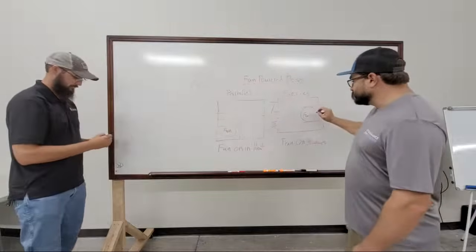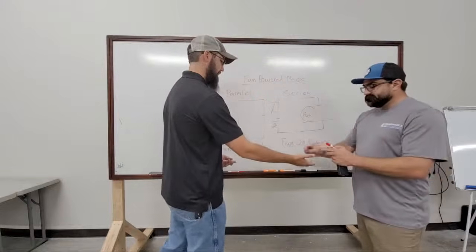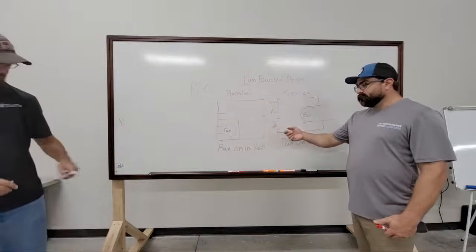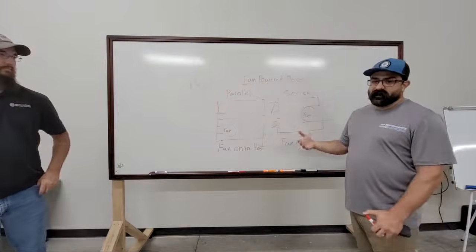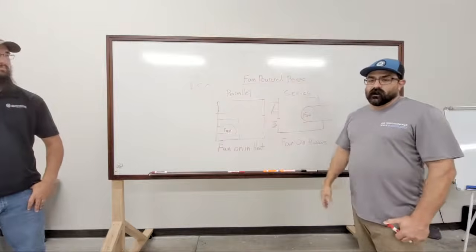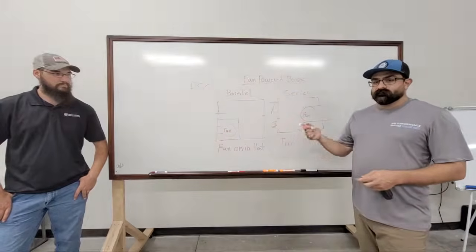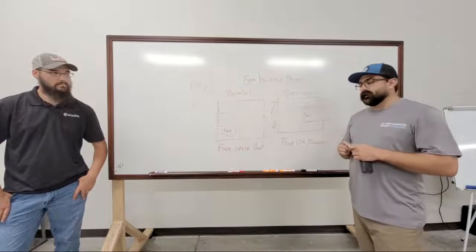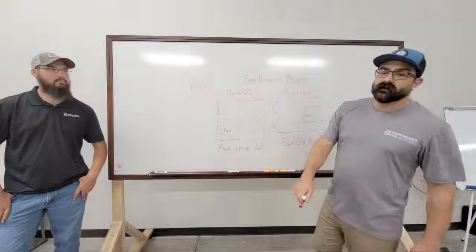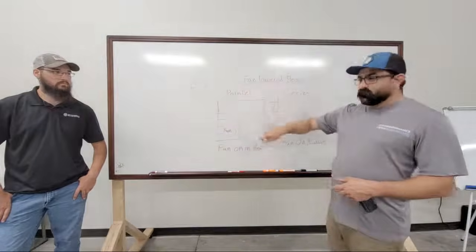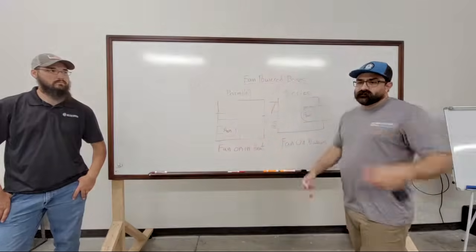But if this fan goes out, you're gonna push everything out that return. So that is kind of, I guess, a benefit in this situation, with a parallel, if you lose your fan, you can still temper the space. You won't be able to do it during heat though, because typically you need the fan to do the heater, because your airflow pickup is typically on the fan side for your safety, not on the damper side. Some of them are mixed up, they're actually on the cabinet, not the fan outlet itself, but it just depends on the manufacturer.